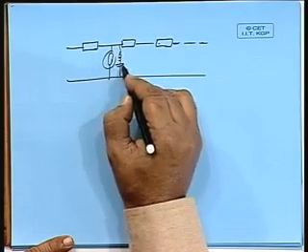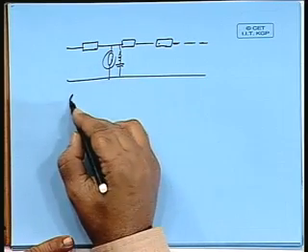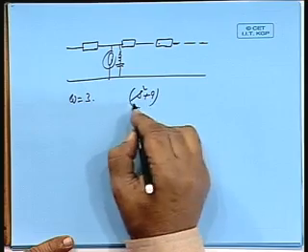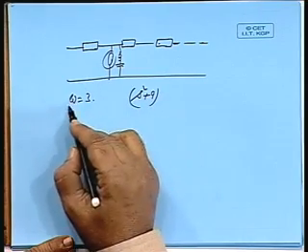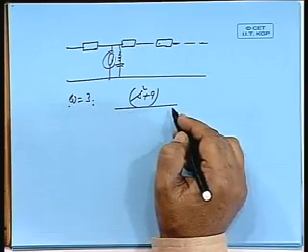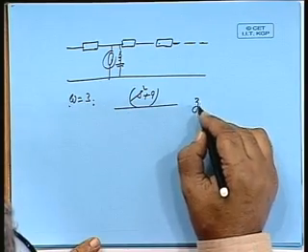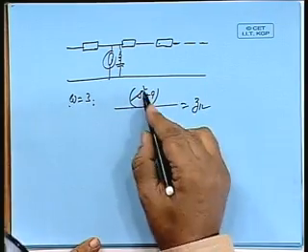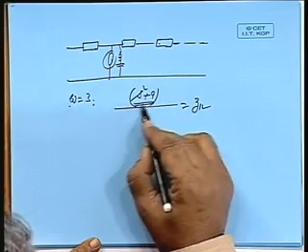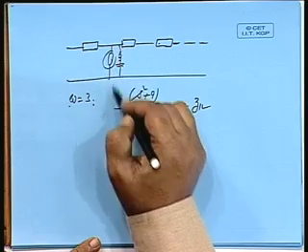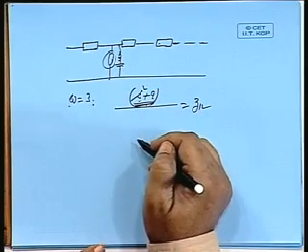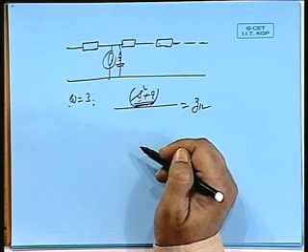Suppose this is resonating at omega equal to 3, then s squared plus 9 will be giving me omega equal to 3. This is the resonating frequency. This will be the numerator. Okay. So, in Z12, if I have a numerator of this kind, s squared plus 9, my target will be to create a 0 in the shunt element such that the elements are having a resonance frequency at omega equal to 3. Is that all right?